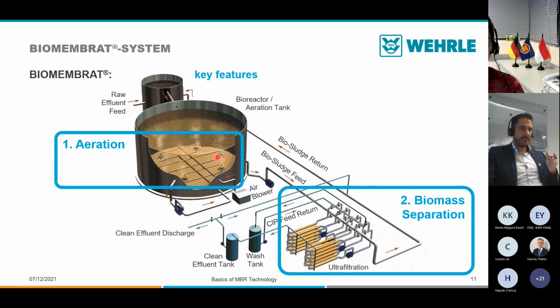If they sit all the time as a submerged membrane in the sludge, the membranes need to bear all the chlorides, all the high COD, all the fouling BOD material. That means the membranes get really high stress. Especially in leachate, we face a lot of TDS, a lot of chloride, a lot of heavy metals. Those metallic substances stick on the membrane. They lead to scaling, which is sometimes irreversible, and the operator needs to replace all the membranes, which is a high cost.